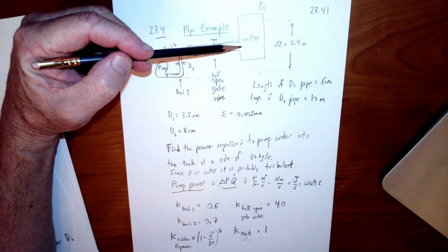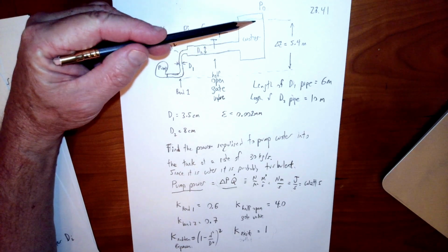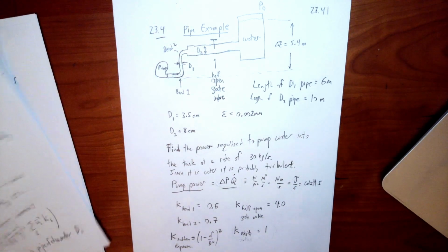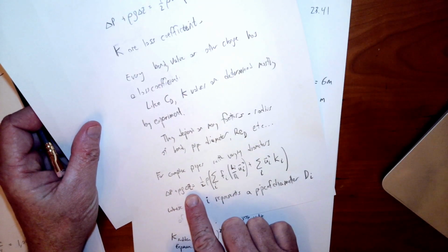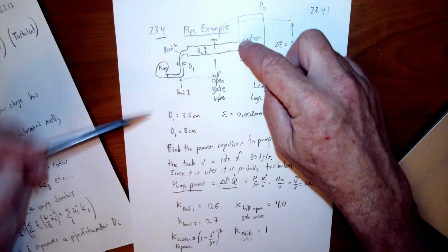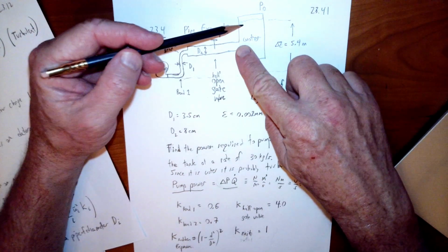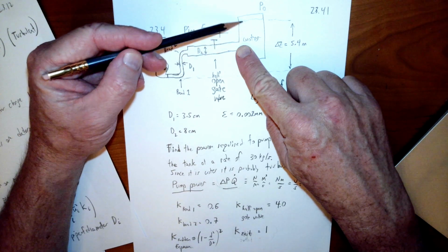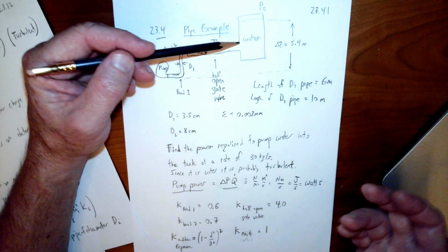And I think if you think about it, you can see that it doesn't actually matter whether we go from the top to here and put that whole rho g Z in this term, or whether we go less high and then add rho g Z to this pressure, because that's what you add to this pressure to get from the top down to here. So it doesn't make any difference.